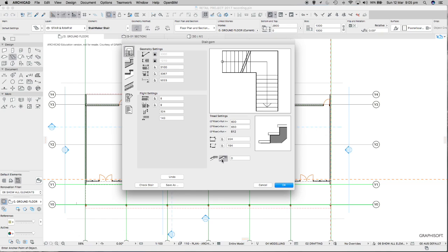Probably the next thing you should do is come down and pick how the stairs land at the top. So we would normally want our stairs to land with the top tread below the floor level, so you step onto the floor for the last rise. Then lock off the tread depth. We'd want that to be a minimum of 250, and then lock it off.